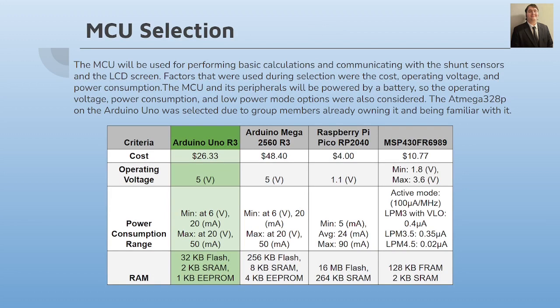When determining what microcontroller unit to use, we used the following factors to make our selection. The I2C peripherals would share the same 2 data pins, while the SPI peripheral would need 4 to 5 data pins. This means that very few data pins are actually needed for the project. So while a higher pin count can allow for later additions, it isn't necessary.